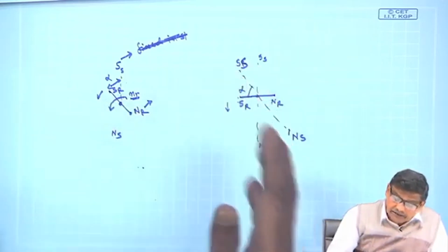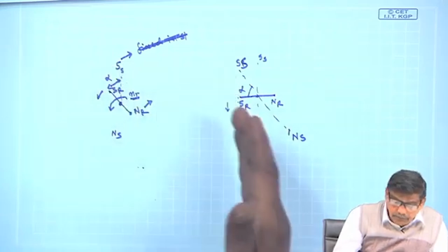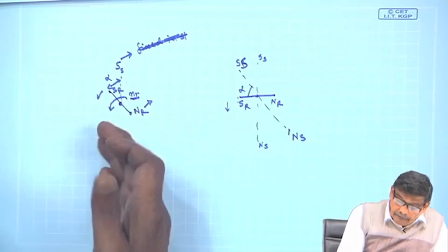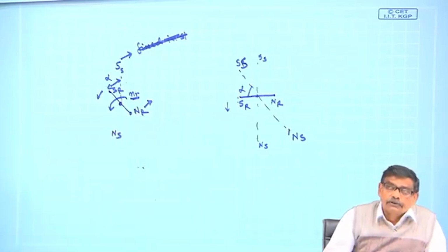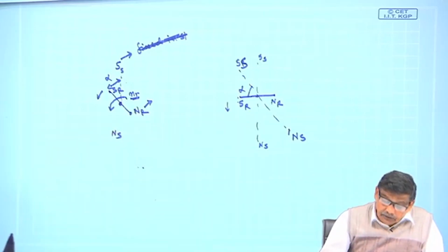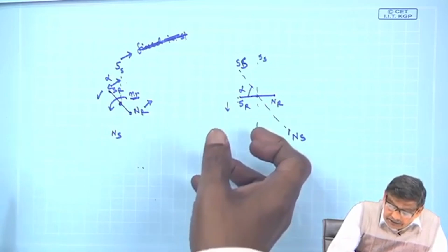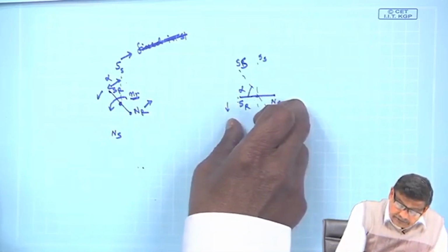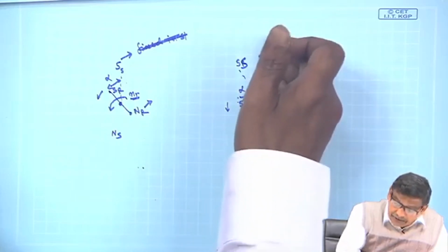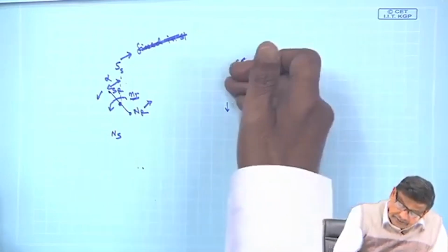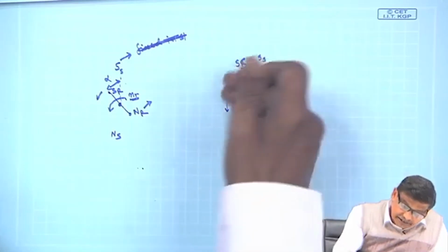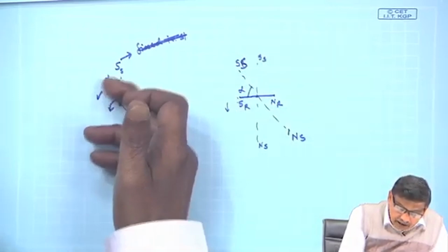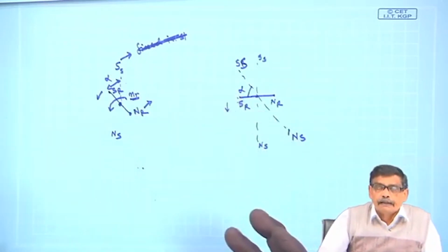So, if somebody says no, the same constant torque is to be produced as when it was producing whatever torque here, then the answer should be that you not only allow Sr Nr to occupy a new position like this, but also advance Ss Ns by such an amount that the angle between these two fields, alpha, remains the same.